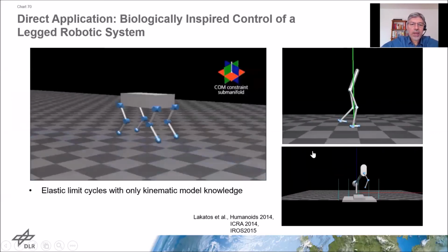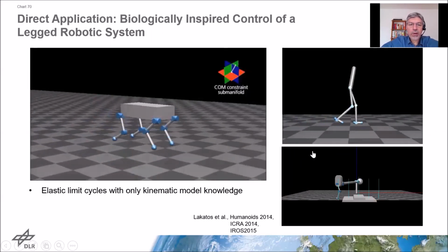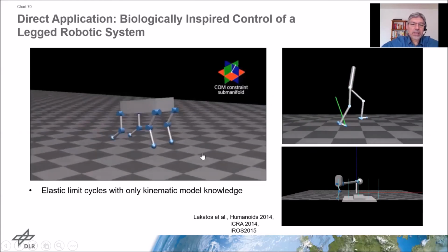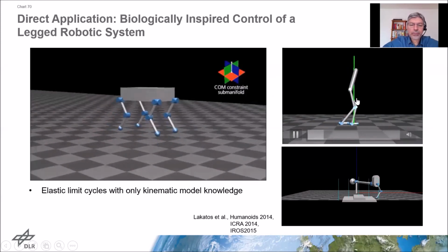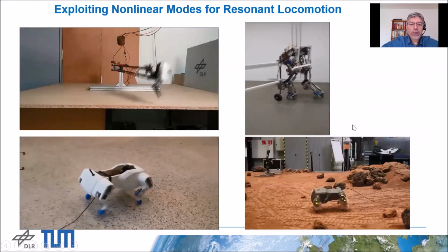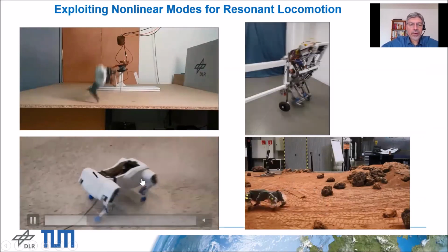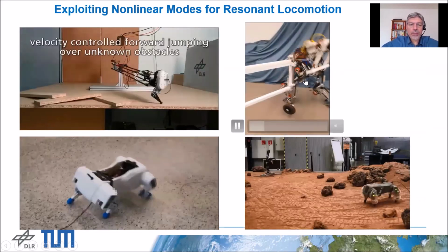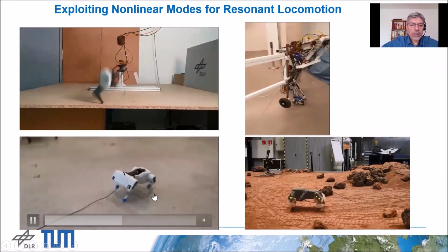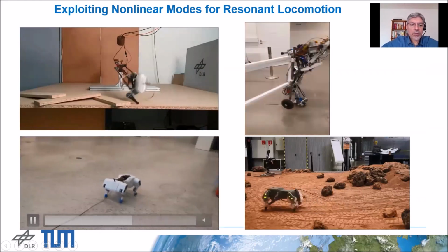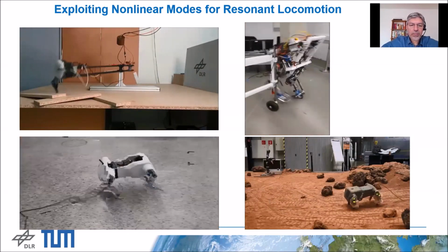And finally, I would like to show some simulations in which we exploited this bang-bang controller in some preliminary work to excite locomotion patterns for quadrupeds or biped robots. And we also apply the same concepts on some prototypical systems of a quadruped or a biped-like locomotion. And here you see that by this concept, we could implement a walking motion, then here a trotting motion, and finally, a bounding motion.